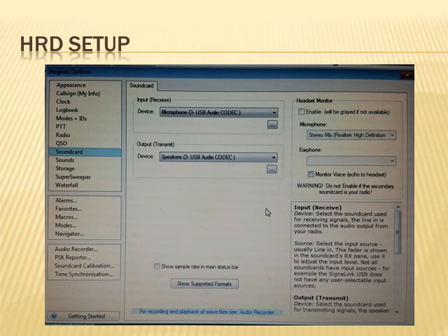By selecting sound card in the left-hand column, we get up the sound card in the center to set up the input receive and the output transmit type of device. So in my case, we have the microphone as the USB, since we want to communicate with the TS590S over the USB connection. All information from our host computer is controlled then through that USB audio connection.